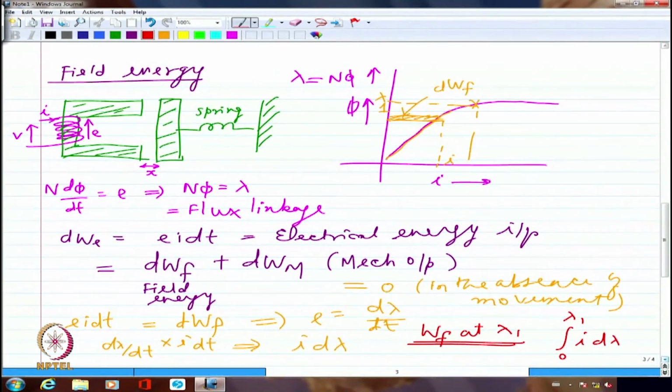The magnetic field lines are going to flow like this, and then flow like this and come back. If I take the average length, Lc is much higher because Lc consists of all this length, and all this length and this length as well. All that corresponds to the ferromagnetic core. The gap lengths are only this much.